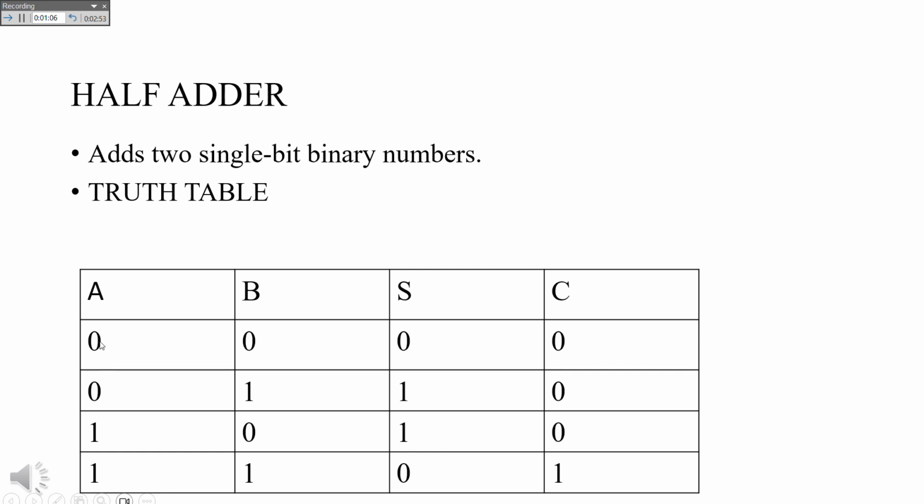In the same way, this A input is 0, and then the B input is 1, which is high. It gives us a high. So from the look of things, we can see that when both are low, they give us a low outcome. When both are high, we get a low outcome. But if one is low and one is high, we get a high outcome or a high output.